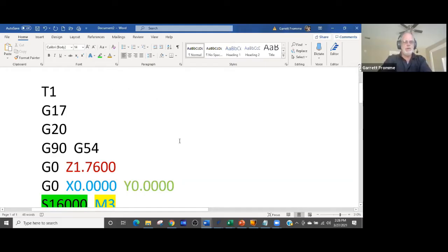In the case of us, the software Vectric will not write programs as one program. This is where your post processor comes in. The post processor for this one, which is a Bob's E4 CNC, tells Vectric, when Vectric tries to write a program,